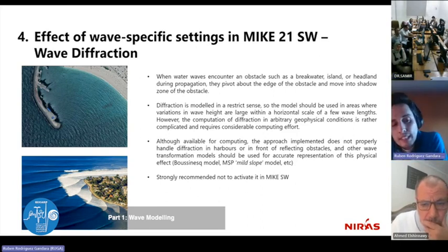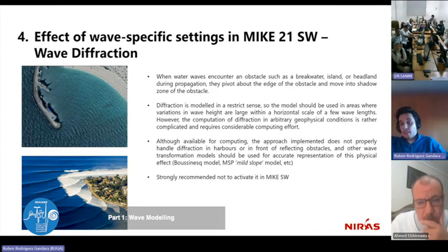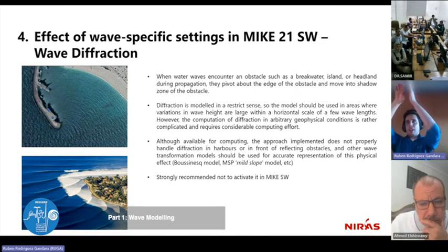So what happens is that when those waves reach the tip, there is a discontinuity in the water layer there, because right out of the tip you will have a wave height of, I don't know, 5 meters, and right next to it you will have a wave height of 0. This is a non-stable regime. You cannot have a vertical wall. You will never see that out in nature. You will have a significant wave height of 5 meters, and then all of a sudden